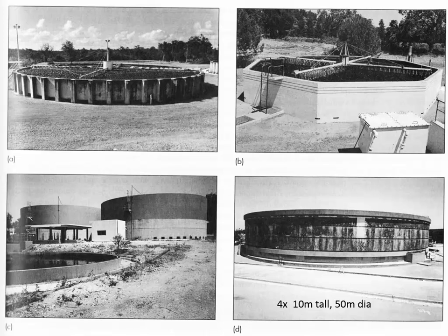They can vary in size from relatively small. You can tell just by the ladder going up to this. You know, obviously the ladder is probably about 1.5 feet wide, so that trickling filter isn't very big. And then this trickling filter happens to be 50 meters in diameter and 10 meters tall. And so it's enormous. In that particular facility, they've got 4 of them that are that size running together in parallel. So they can really cross the whole spectrum of everything from small to big.